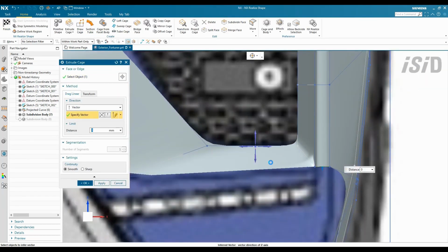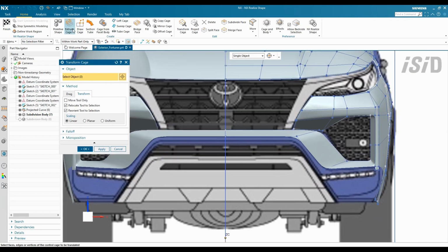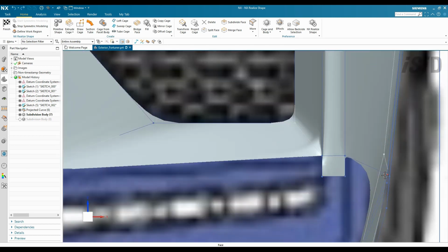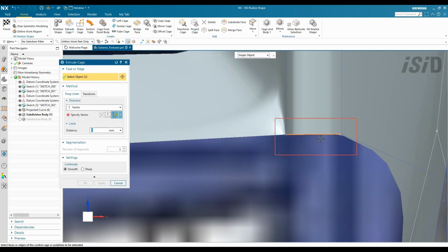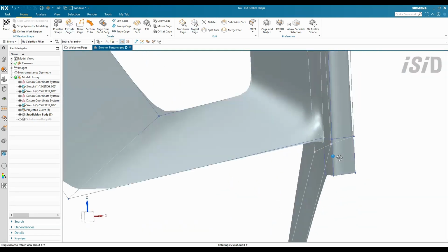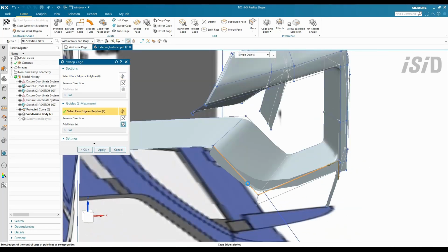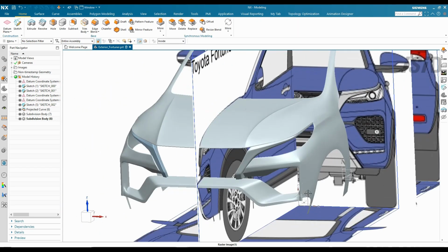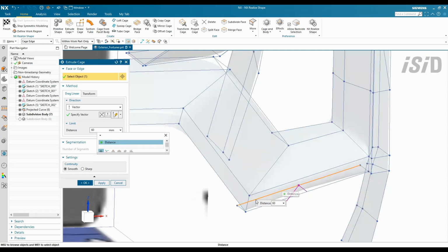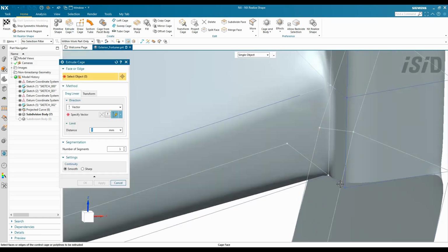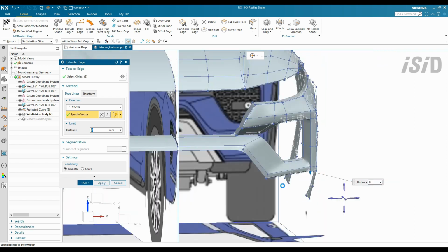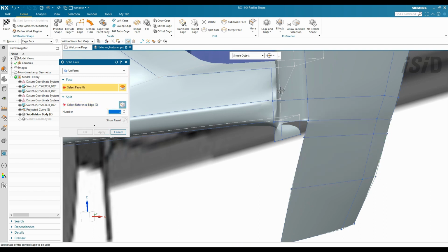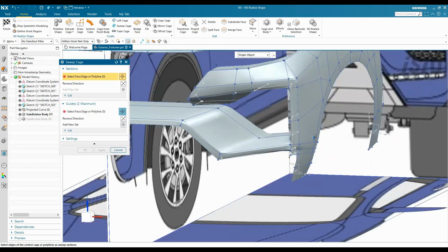Okay, and then I add more surface again for this area using a combination of extrude cage command and sweep cage command. Add more refinement using set weight command, and again adding more surface using extrude command. So the workflow is almost typical for all the surface creation.